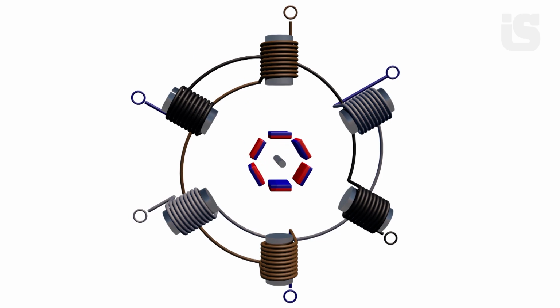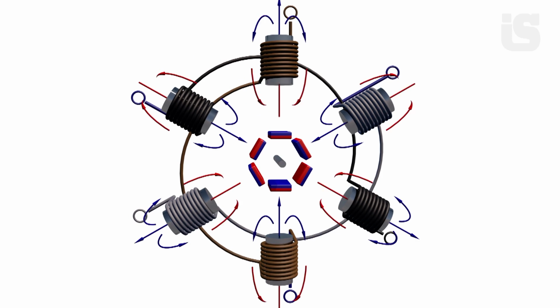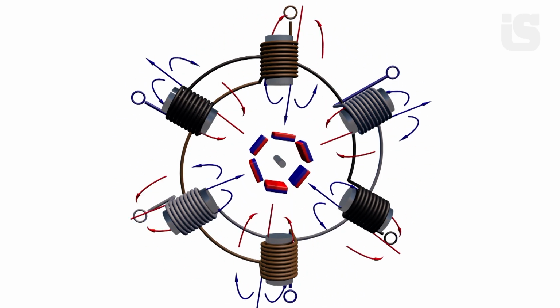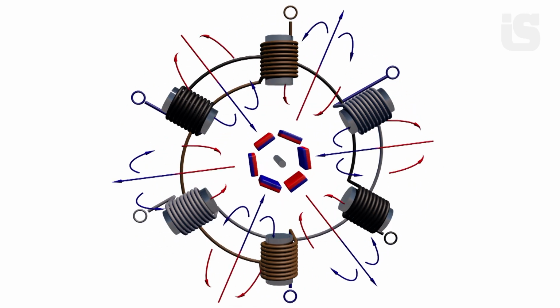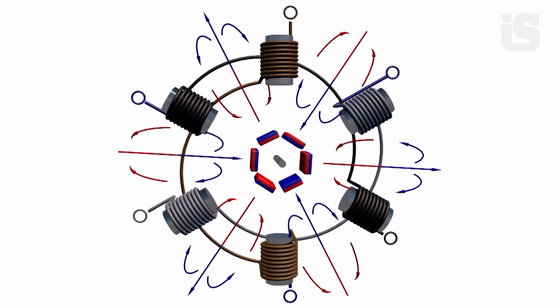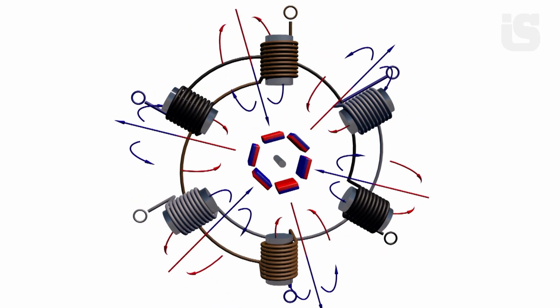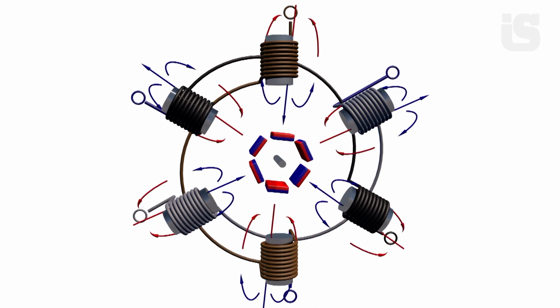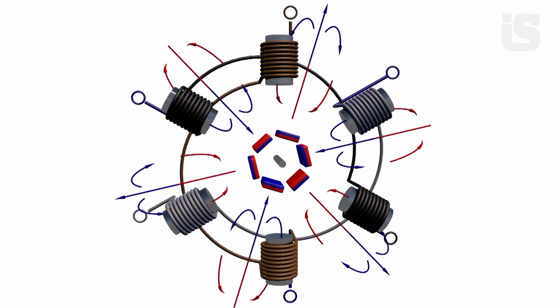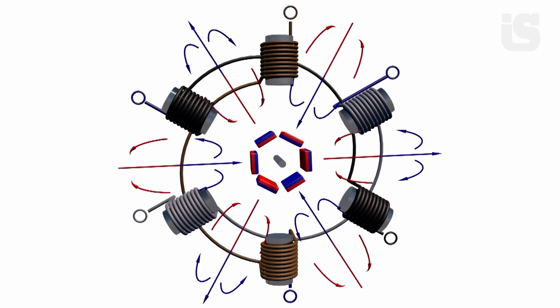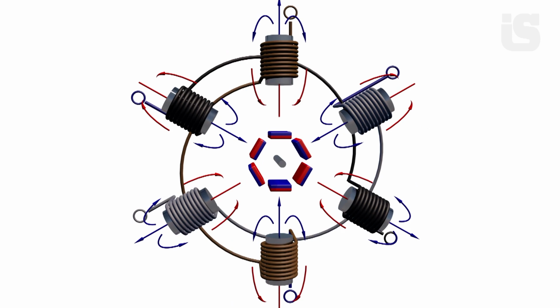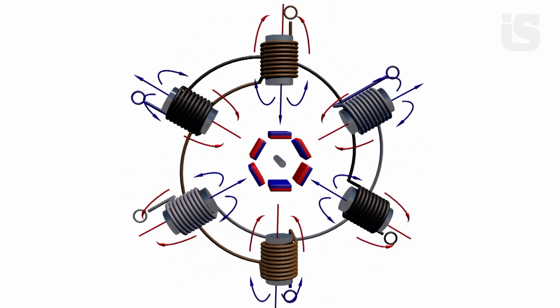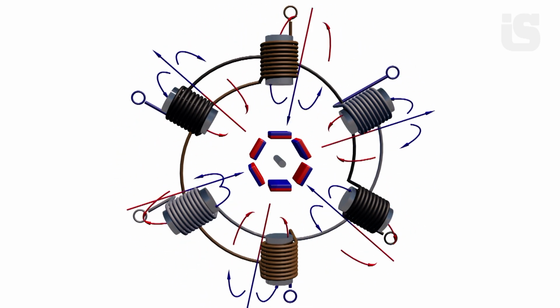Earlier, for simplicity, we considered the rotating magnetic field of the stator as a single entity. But we actually have three pairs of changing fields. The displacement of these pairs of fields can be visualized as a rotation from one pair of magnets to another. The rotor's magnetic fields will be attracted by the rotating, opposite fields of the stator. The rotor will rotate, following the stator's fields.